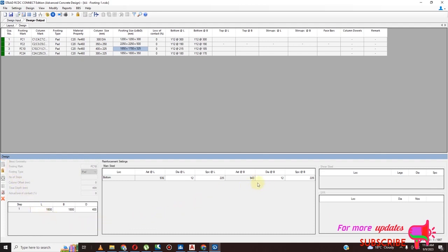So you can see it's giving me 12 at 25, 25. Very consistent, very uniform. Uniformity. We need uniformity. That's why we need at most fewer than 4 types of bases, and we also need uniformity in reinforcement. You don't need to confuse those working on the construction site.